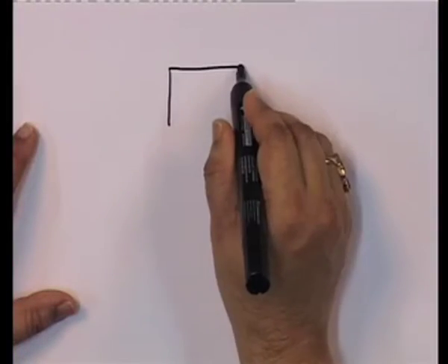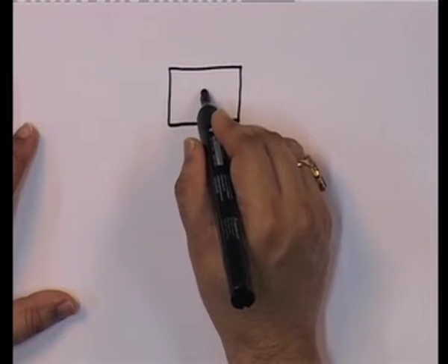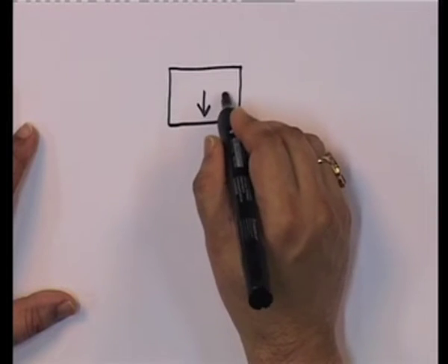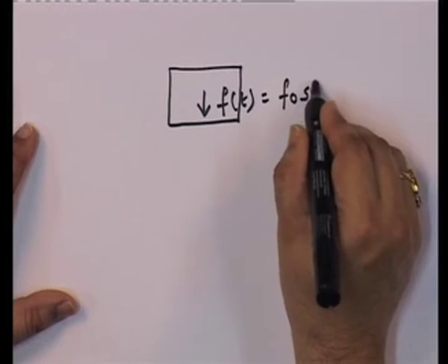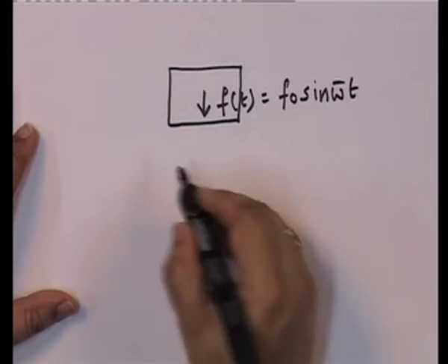That's a simpler problem for us to understand, because for the base isolation problem, I'll have to start defining some new parameters. So, before I do that, I will look at the force transmissibility problem. If I look at it, it becomes the following. I have equipment which is transmitting a force F of t is equal to F0 sin omega bar t.